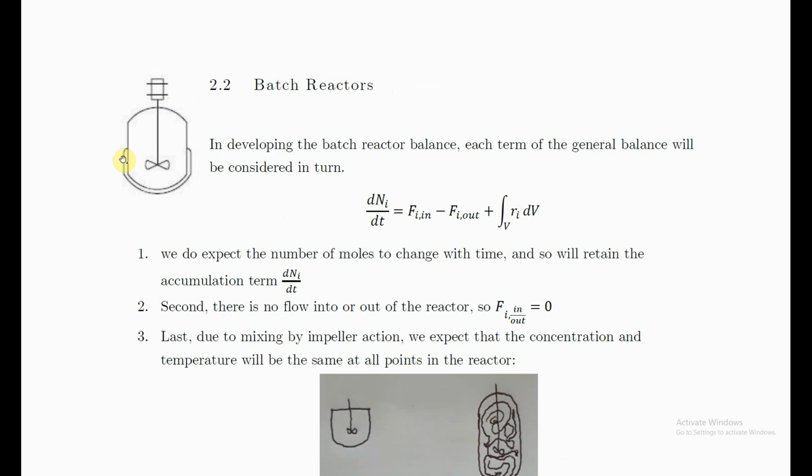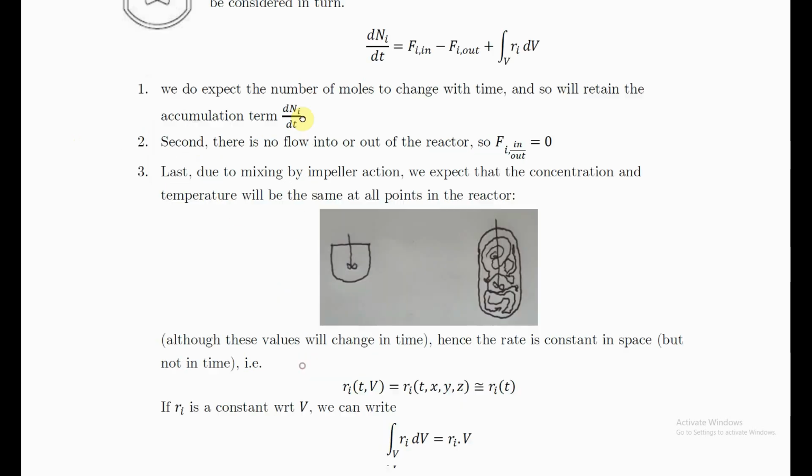It's going to be the volume of the vessel on the inside. If it was a liquid reaction, happening in the liquid phase, then there'll be some liquid level, and if it's operating in batch mode where we aren't feeding liquid in or withdrawing liquid out, then that level might stay constant, and so the volume of that liquid is going to be a constant.